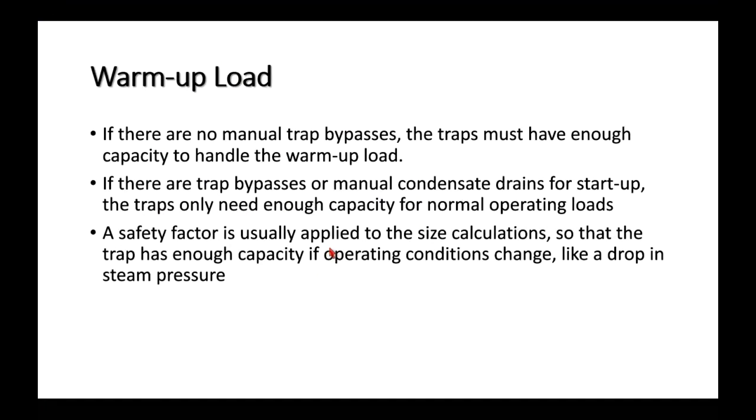So let's talk a little bit about subcooling and saturation curves and how a trap may track that saturation curve, or it may have a fixed temperature discharge, and then what are the consequences of each type of trap in terms of how they respond to that saturation curve. And whenever we're talking about that saturation curve and having a trap that tracks it, really what we're talking about is a trap that relies upon subcooling to discharge.